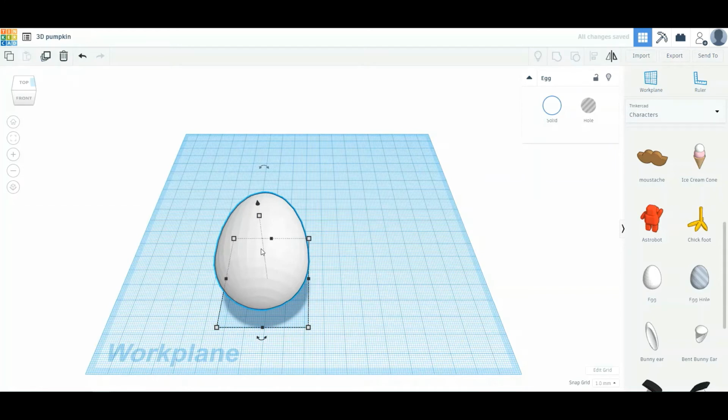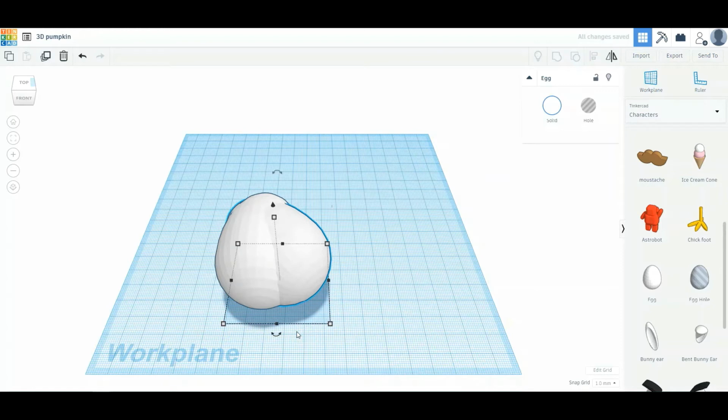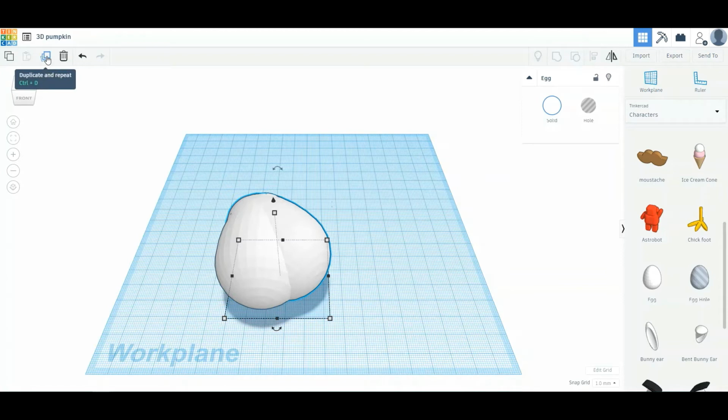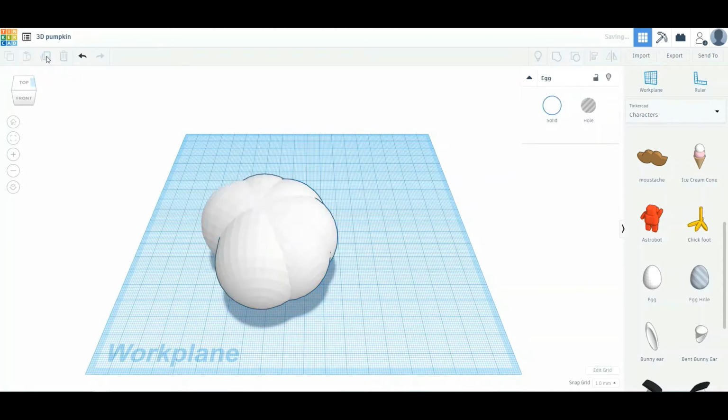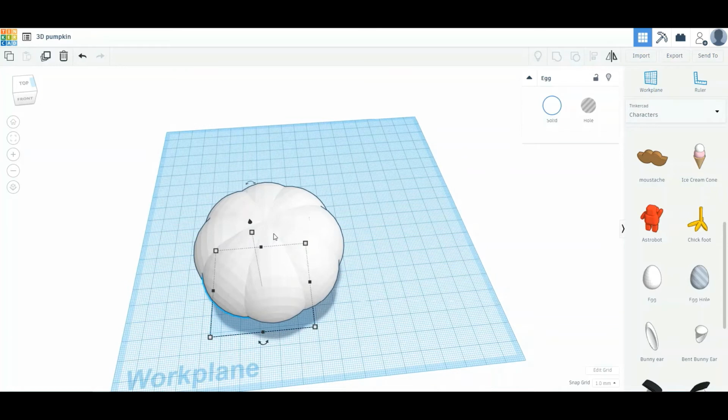And it didn't really look like it did anything, but what you'll see next is the offset version of it. So again, we'll hold Shift down, click on the two arrows and rotate this 45 degrees. And then next we're gonna click the arrow right key 6 times, and then we're going to press the forward arrow key 3 times. And now after that, we're going to go back to the duplicate button and hit that 6 times. And so as you can see, we now have the basic form of our pumpkin. Now if you clicked a few other times in between some of those steps, it probably wouldn't have duplicated the right way. So you may have to click undo a couple of times to make sure you get it right.